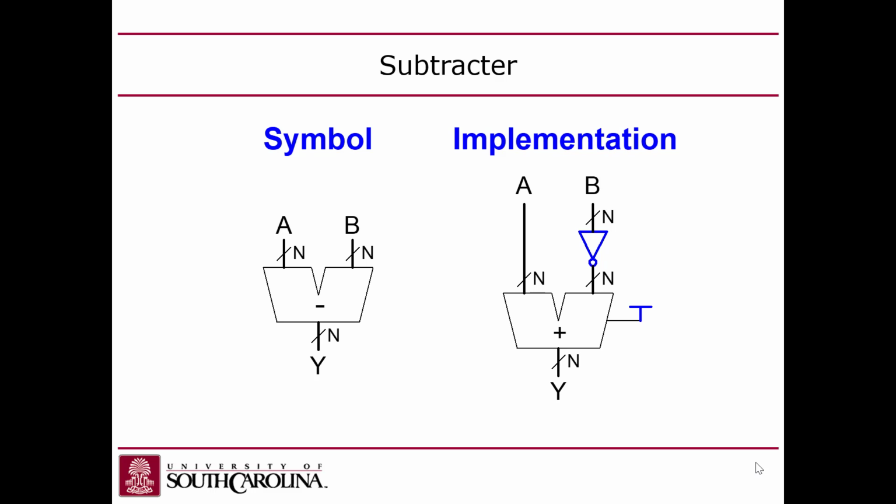You can add two values, but if you want to subtract them, you can convert b to a negative value, negate b. So how do you do that? You take the 2's complement of b. That's like saying not b plus 1, where not b is the 1's complement. That's where you take the complement of each of the bits in b, and then you add 1.